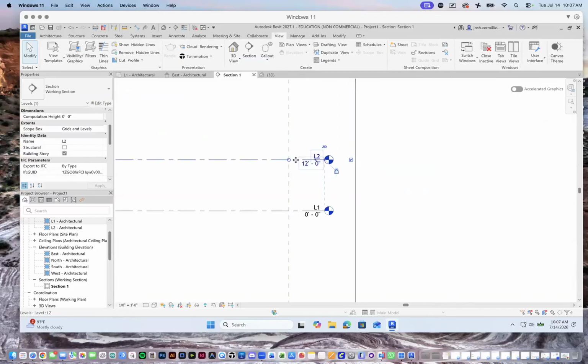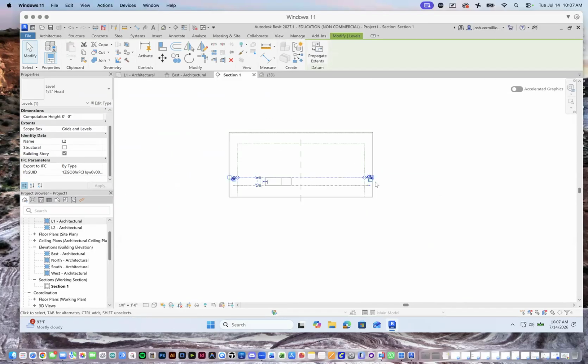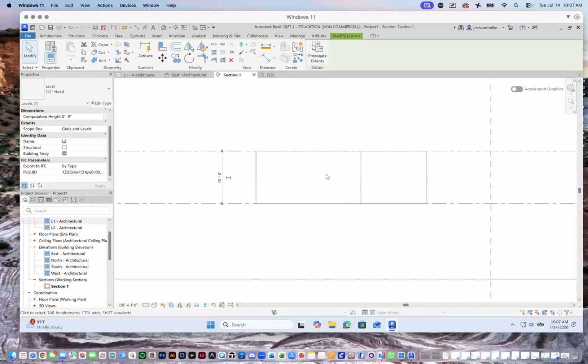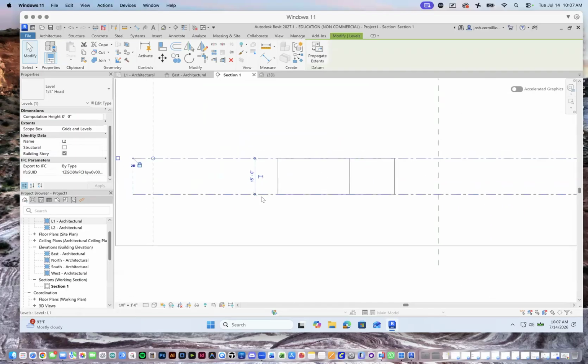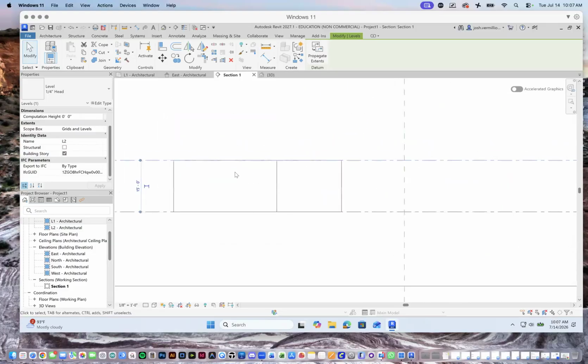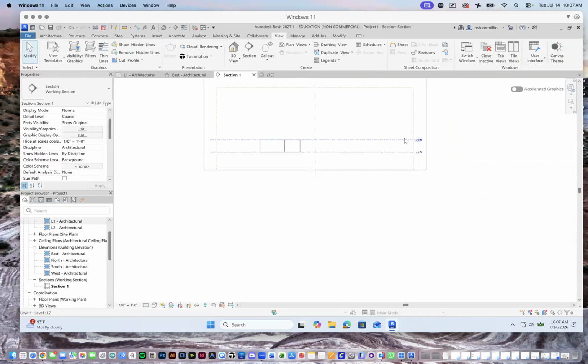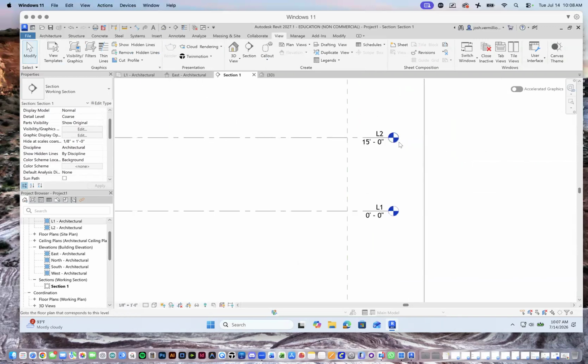And what happens now if I change, let's say my floor to floor height? Let's say instead of 12 feet, I'll just unclick this. I'll go up to here and I'll say, actually, I want 15 feet floor to floor. You can see that as I change that height, because I didn't say the wall is 15 feet or 12 feet tall, I said it goes from level one to level two. If I change where level one and level two are, everything is associated with those levels and everything changes and modifies with it. Okay. So suddenly now I have 15 feet high walls, not because I told it it's going to be 15 feet, but because I moved the distance between level one and level two to 15 feet.